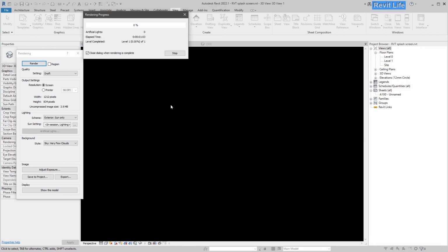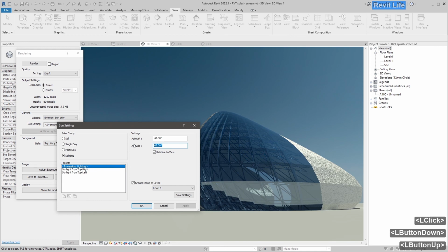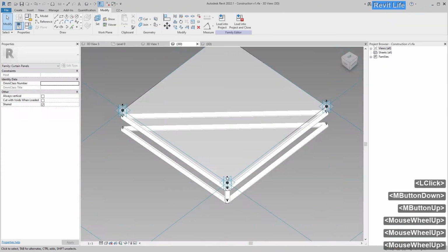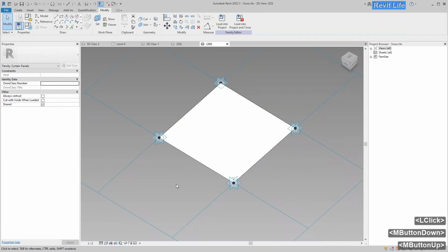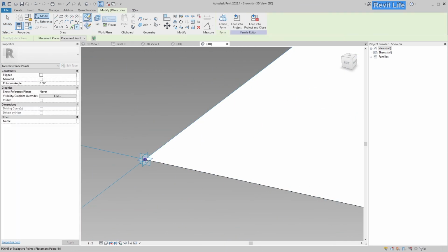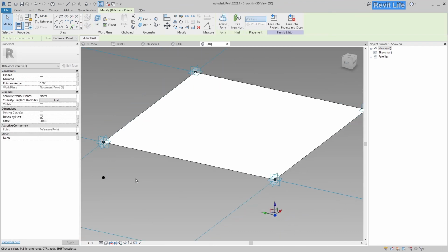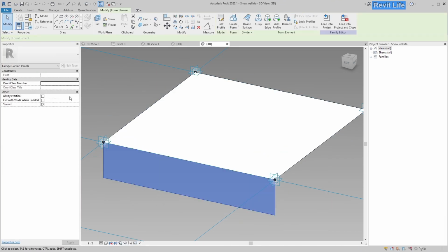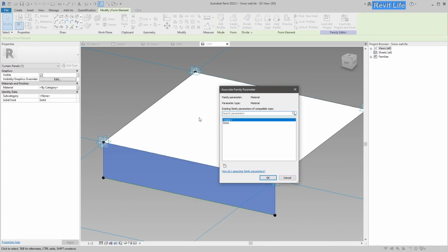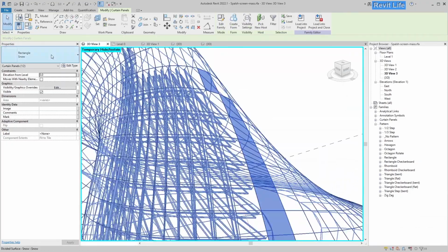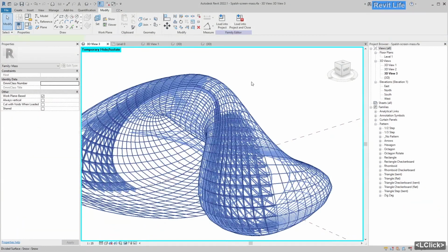If you have to re-render every image, it takes about a minute for the image to render, or maybe a bit less, and then I have to change the sun's position, and re-render the image. And here I figured out that I need another family. This was the second family I mentioned, the concrete family with the side, and this is the side of the side panel where the glass meets the concrete. So it just doesn't float in the air, but it kind of pushes against the side of the concrete. Here you can see that this is the side panels that I'm selecting and adding this side concrete slice.